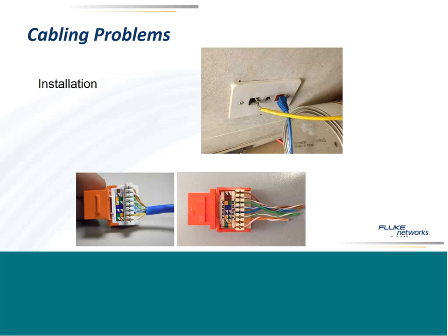Installation. Now, if you go to a Cabling Installation and Maintenance magazine or on Reddit, you can see a parade of cable installation horrors that will stand your hair on end. I just grabbed one picture here. I think there's some fine twisting there. You know, the pairs need to be twisted together, not everything all twisted together, as you see on the top there.